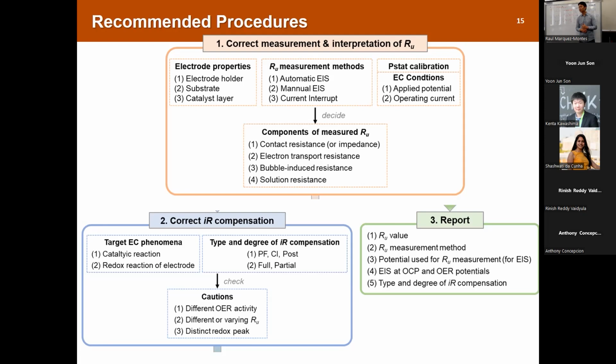The electrode is one of them. So if your alligator clips are growing things and look all gross, that's bad. Yeah, that's definitely bad. I have experience with using a rusted copper alligator clip, and you start to see very interesting impedance. Yeah, the first semicircle will change with time, and change with your electrochemical condition. Got it. Cool. I'm glad I came.